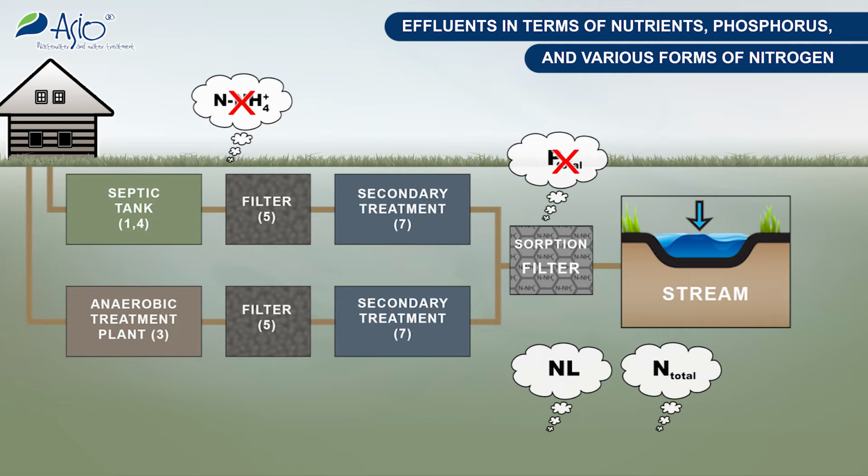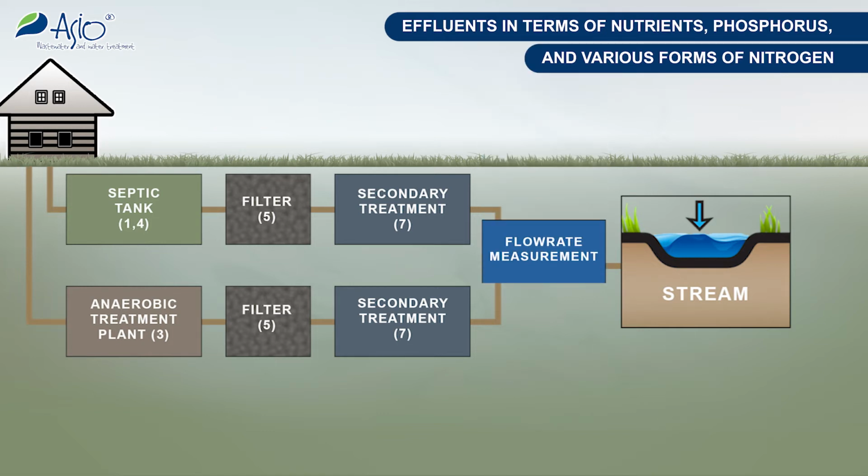In case of larger treatment plants, the quantities of discharge water are taken into account. A measuring unit is usually placed at the discharge where, for instance, the Thomson triangular spillway represents suitable equipment. In case of a smaller plant, these quantities are measured indirectly, for example, from the water consumption.